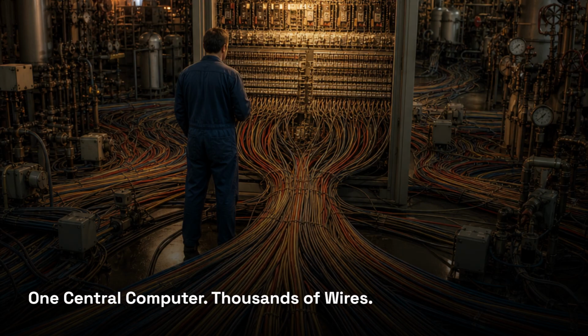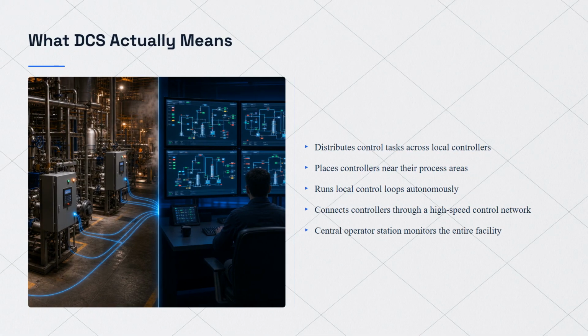The answer was to distribute control. Move the decision-making closer to the process. That is what a distributed control system does. A distributed control system is a computerized platform that controls and monitors continuous industrial processes by spreading control tasks across multiple local controllers rather than relying on one central computer.